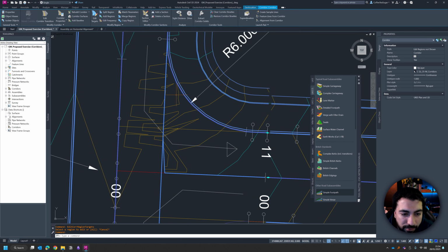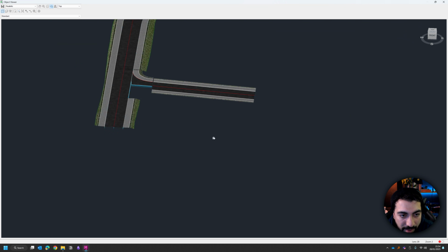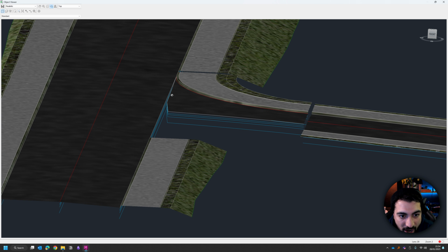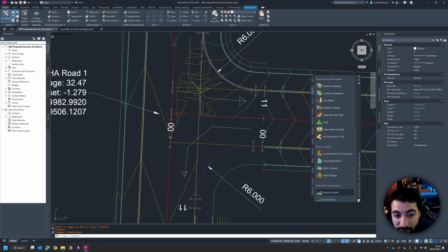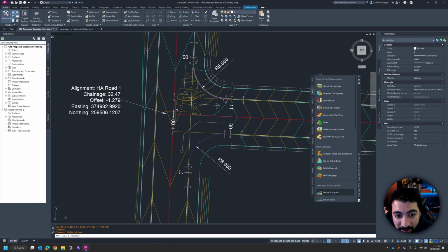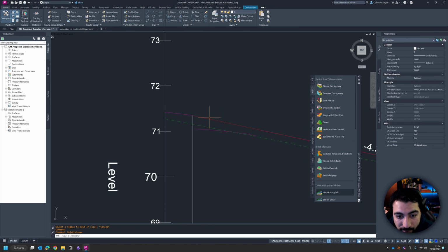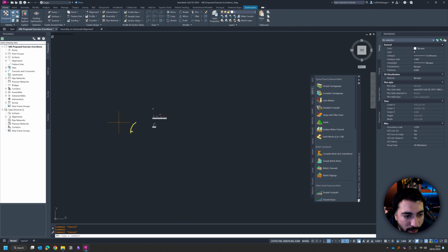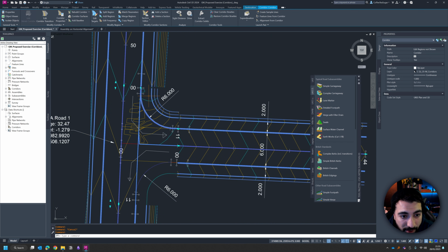Now, in order to fix the levels, the reason they're breaking is because we did not target the right things as of yet. So we targeted the width, but we didn't target the right point. And we need to also make sure that our vertical profile ties in well with the channel line. So let's go and check if we have done that correctly. Now this one is corridor surface road 2. So let's go and select our corridor. Just want to double check if it's done correctly first.